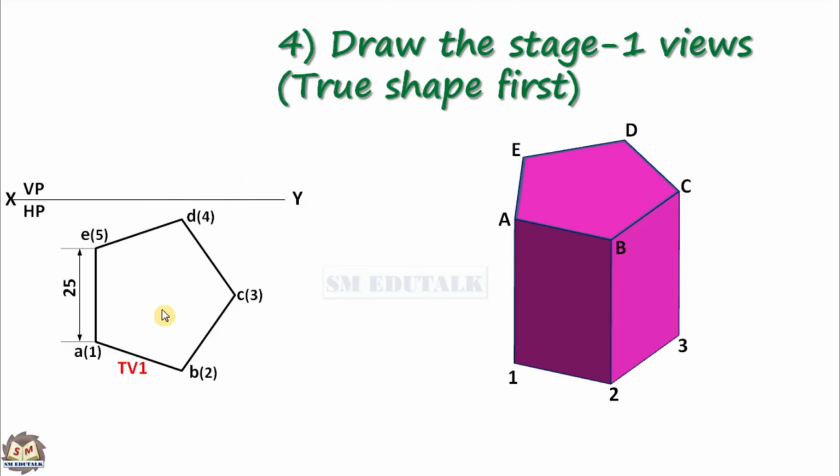You have to locate the center of the pentagon in top view to draw the axis line in the front view. To do so, draw a thin line that connects the midpoint of any one edge of the pentagon and the opposite corner. Similarly, draw another thin line that connects the midpoint of another edge of the pentagon and the opposite corner. The intersection point of both the lines will give you the center point of the pentagon. Draw an axis line vertically upwards from this point.